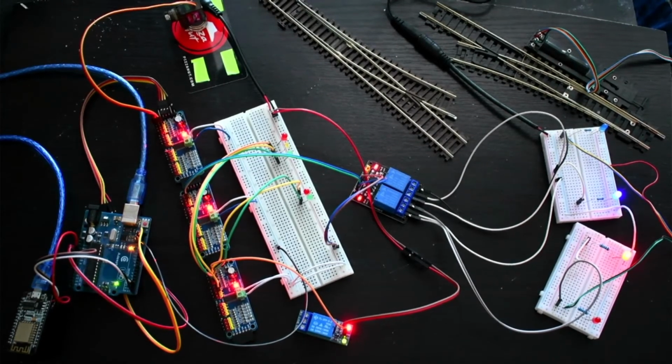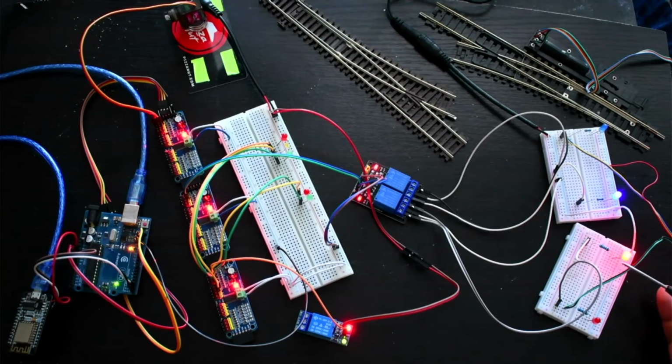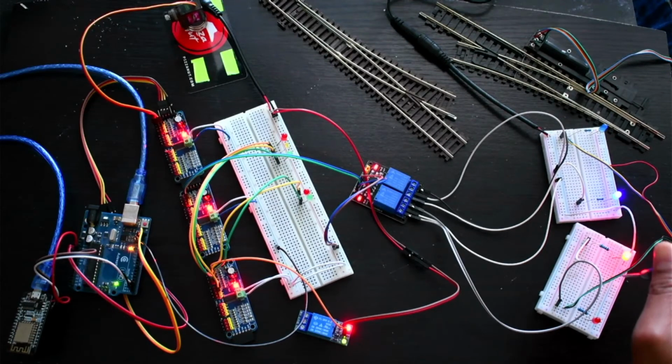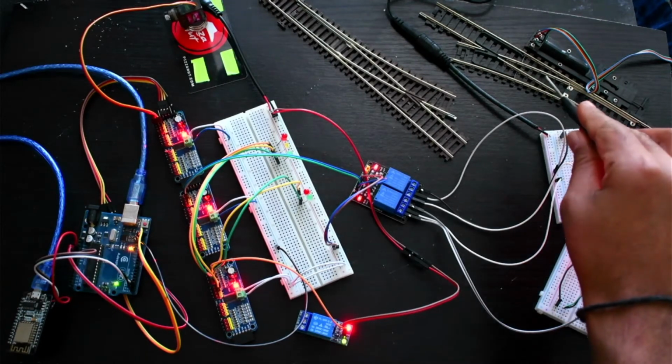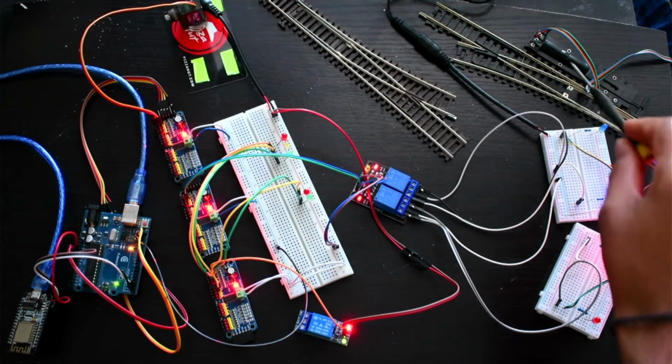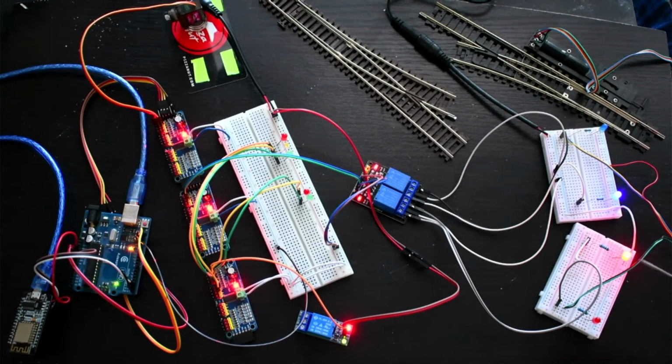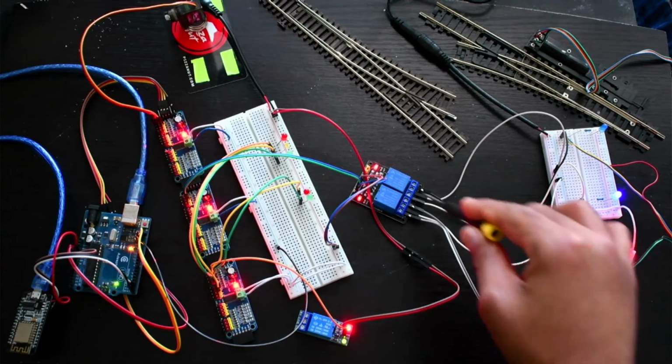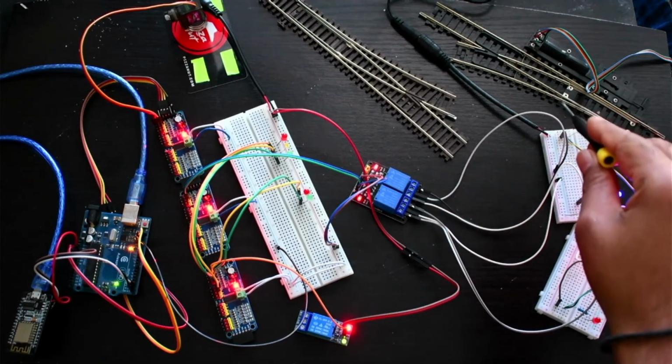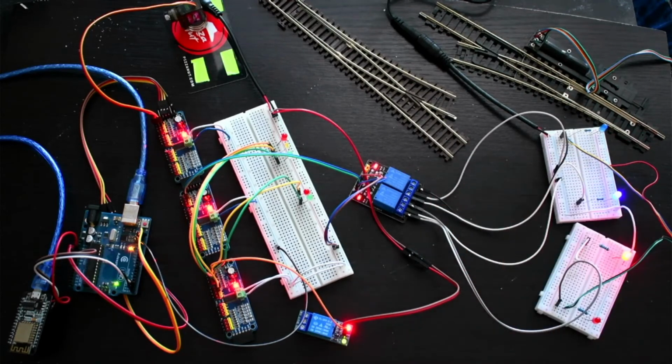So what will happen, whenever the turnout is activated, it will switch for about 60 milliseconds and then go back. Meanwhile it will power up, do the change, and go back. But if you put your wire into the wrong one, it will burn the solenoid of this turnout. That's how you can figure out which way you have to configure your snap turnout via relay switches.